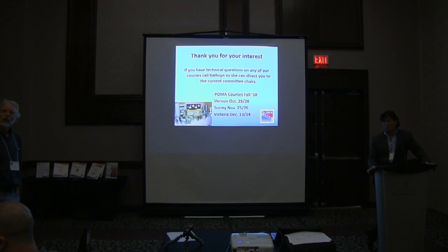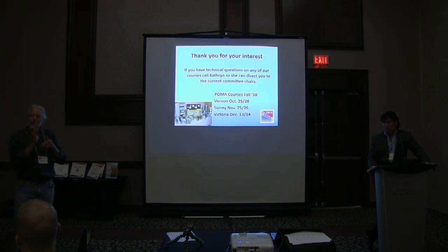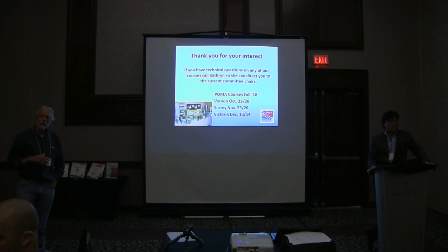Well, see, that's a trade-off. The finer the media you have per square inch, the greater the pressure drop. Typically, the higher MERV filters will be deeper, and there'll be finer pleats to try to combat that. Some people sell 13s and 15s, and a lot of those guys are selling them as better. They think they're buying a better filter because it's more expensive, but now they're dealing with higher static.